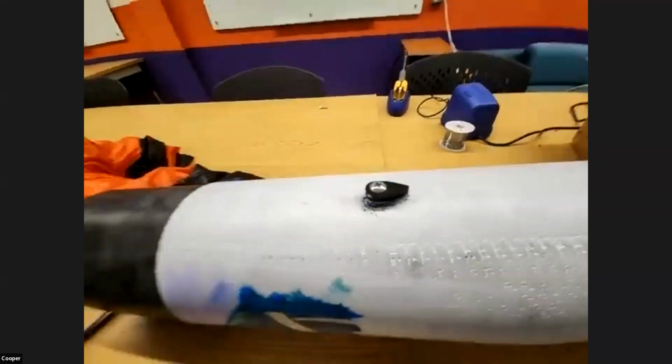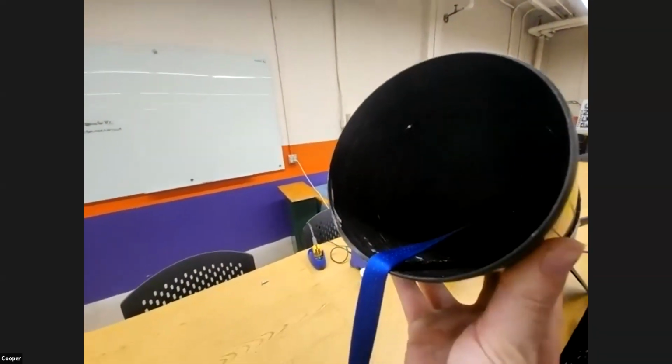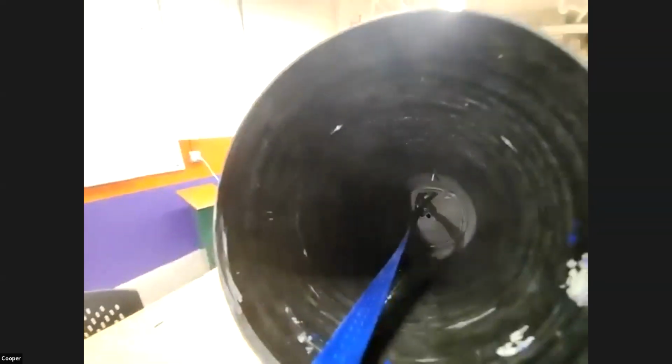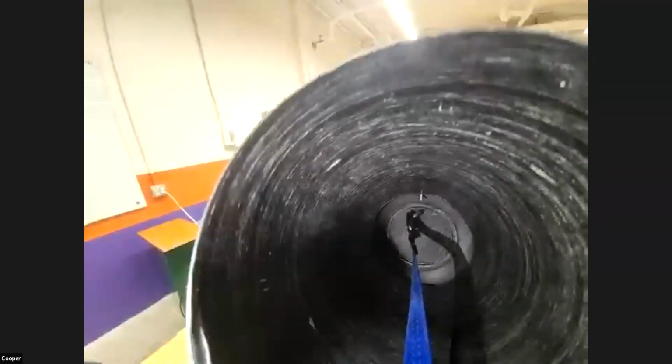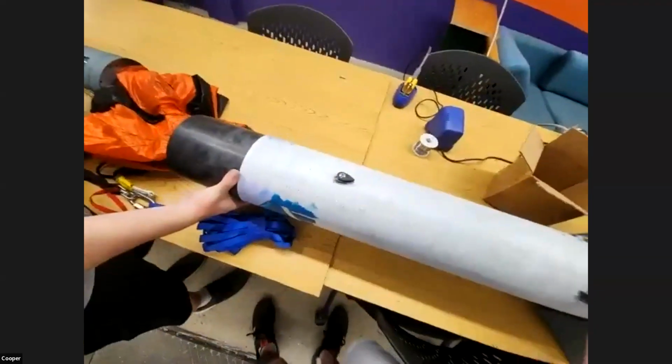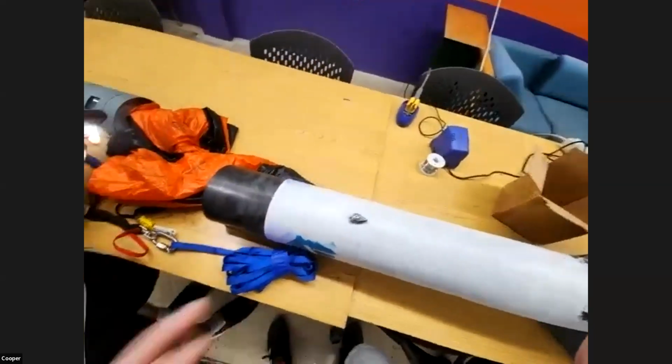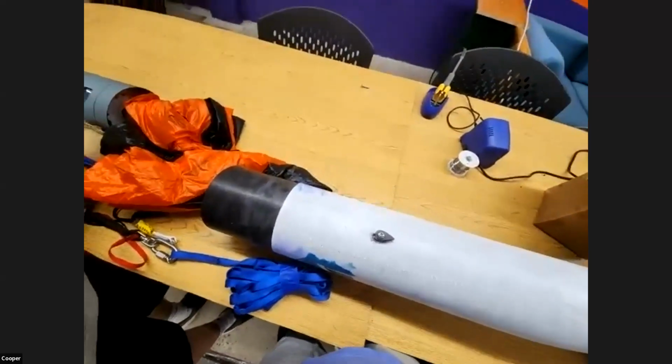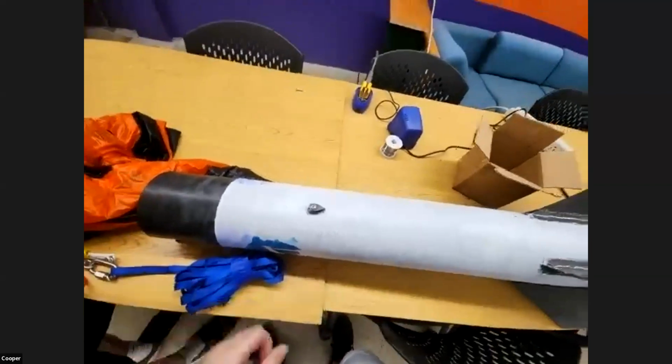Okay, so recommendation from our side, instead of just a nut, if you add a washer, especially a really wide washer, maybe bend that washer so it sort of maps to the inner diameter of the tube. Also, you want to cut the dimensions. You don't want that nut sticking that far down into it because it can cut shock cords and create all sorts of havoc.